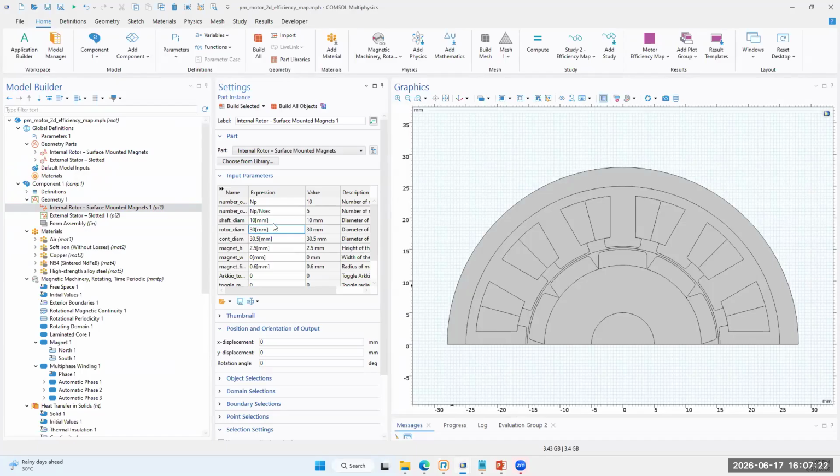And the next question was to understand which parameter will play a major role. One way is through a parametric sweep. One is from a theoretical understanding of which parameter is going to influence my result. The second would be from the parametric study or the optimization study. And there is another aspect called uncertainty quantification available within COMSOL.